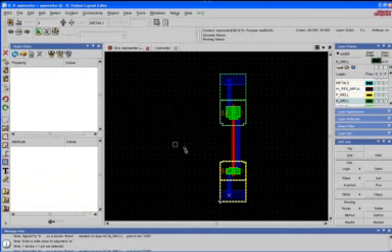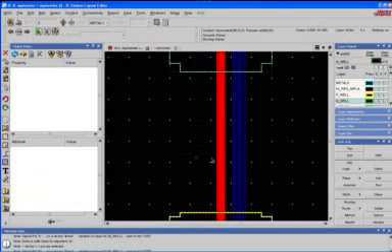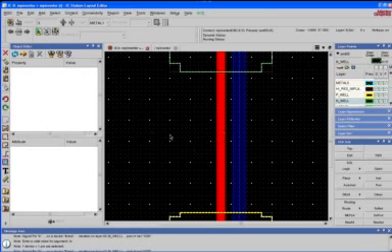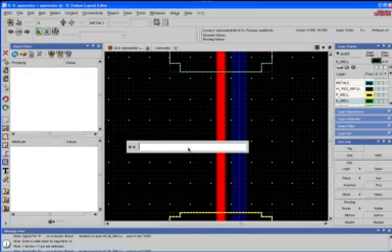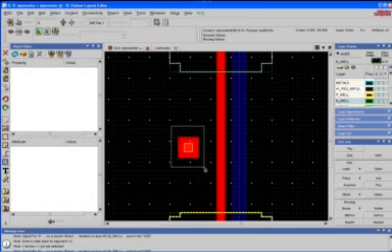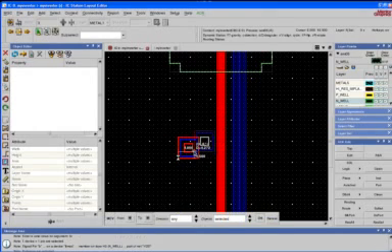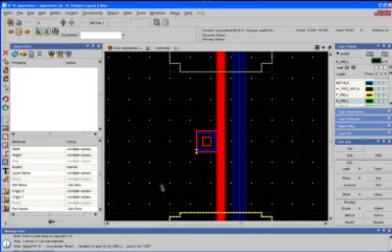Now let's zoom in a little bit. Let's create a poly contact. So we have the poly line for the inputs, but we need to bring in the input from metal 2. So let's create a poly contact first. For that, bring up the command bar by pressing space, type in PC, enter. Let's move this closer and abut it with this.